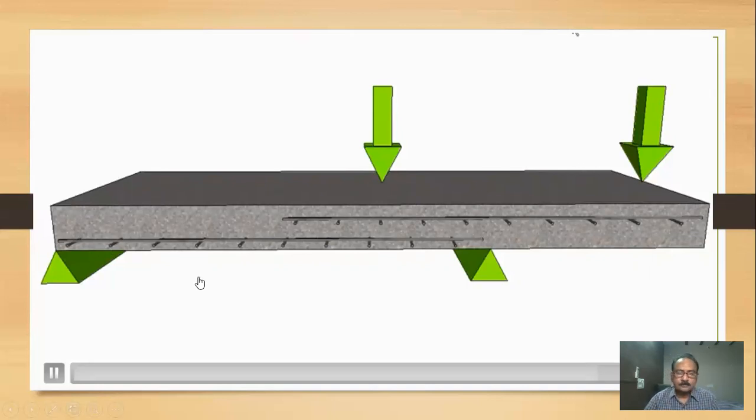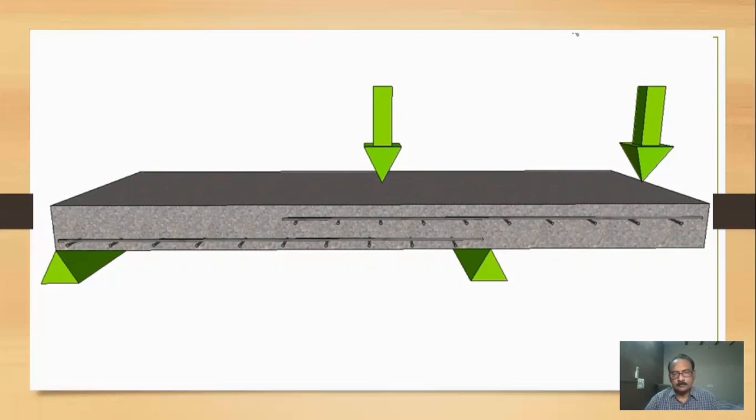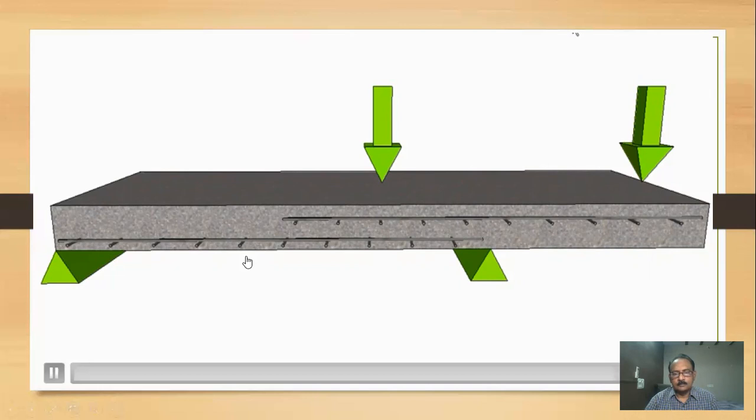This is where our structural engineers can advise us where to place our steel and what size it needs to be. Hopefully that shows you the relationship between the concrete and the reinforcement in a reinforced concrete member, and that we are using the best properties of both materials to form a highly efficient and very popular building component.